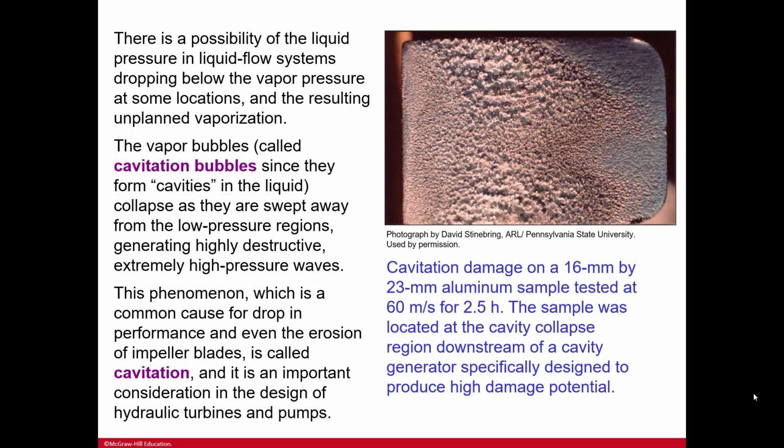You can see kind of a wave formation here. You can see waves in it, right? That's where the destruction is. It's a phenomenon which is a common cause for drop in performance and erosion of impeller blades, and that's called cavitation. It's an important consideration in the design of hydraulic turbines and pumps. And so there are ways to mitigate that.